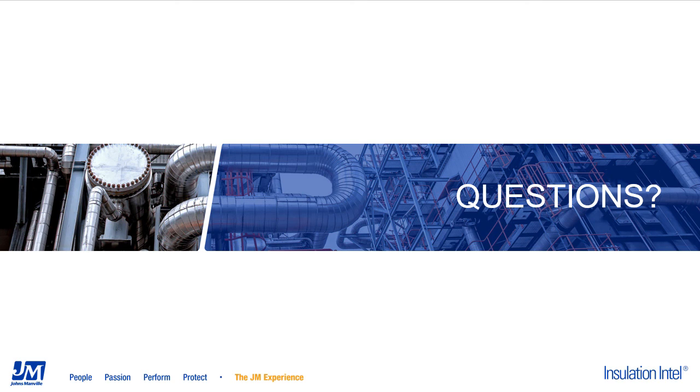I don't know that it's as much an issue of something inherent in the chemistry of the mineral wool material itself as it is just the fact that with your mineral wool systems and historically mineral wool not being water resistant and being a completely open cell or fibrous material, it would have a higher tendency for water to get into the system and bring corrosive compounds with it, and therefore create an environment where you might see a higher tendency for corrosion to occur in a system that is insulated with mineral wool than you might with other products.